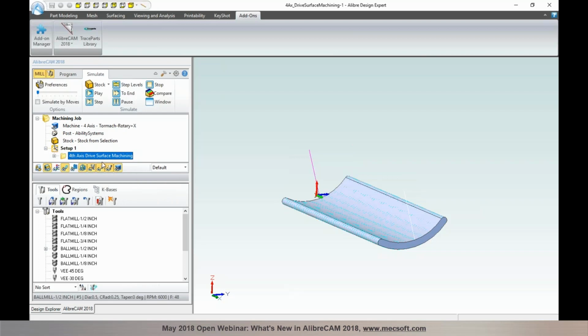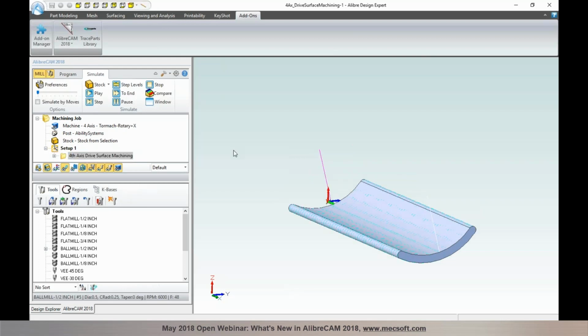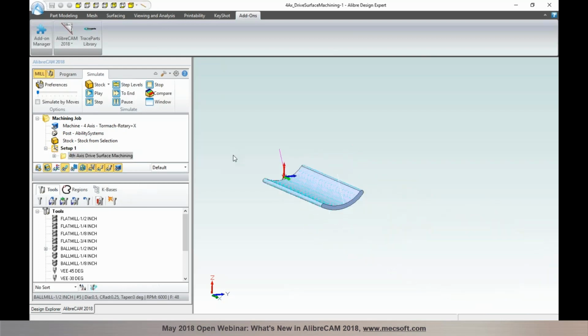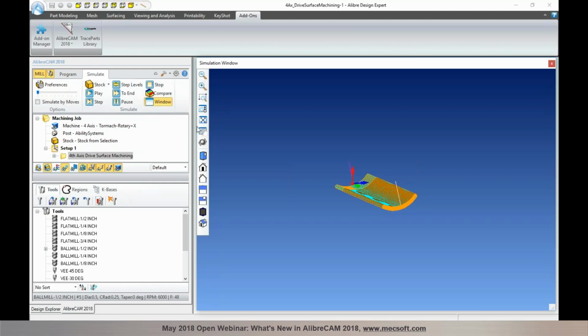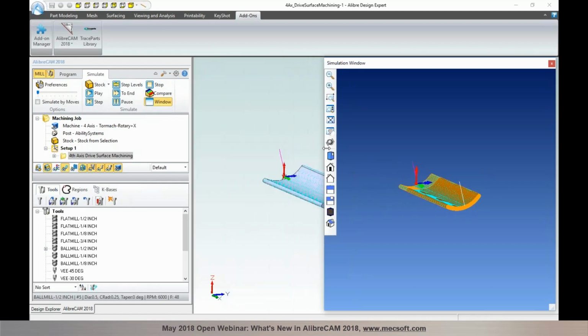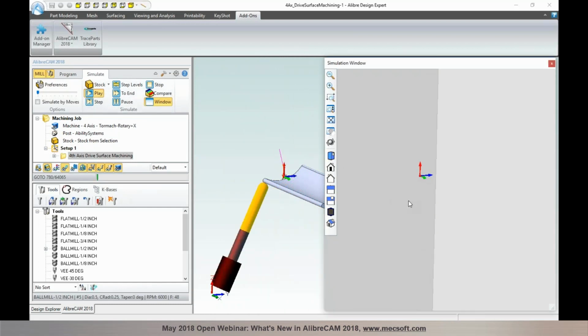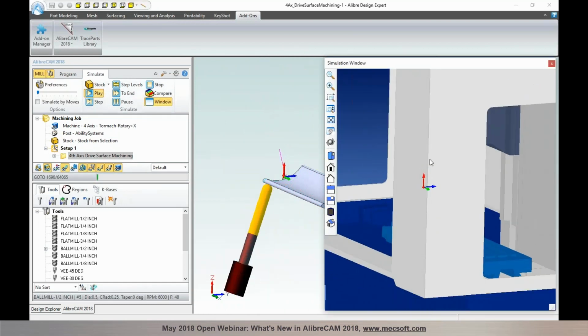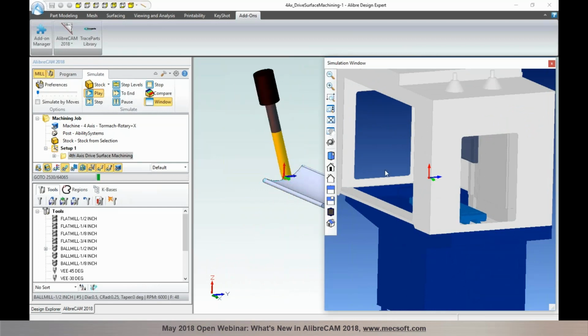In our other toolpath methods, usually what happens is the Y or the X, depending on your machine tool configuration, is locked. So the tool moves in X and Z in the case of a rotation about the Y-axis, as well as a rotary axis. So in reality, you're getting a three-axis, even though it's a rotary motion. But here in this particular toolpath method, you're getting all four simultaneously moving axes. So hope that explains that a little bit.